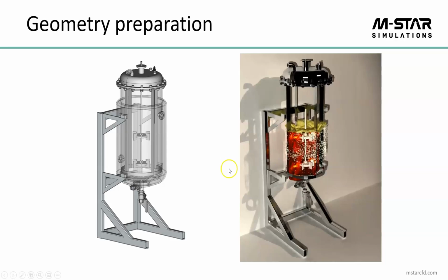If I were in the lab, I might use a laser or LDA to characterize the velocity at one point. I might add some dye to characterize the blend time. I might use a torque cell to characterize the shaft impeller. I might use visual inspection or video to characterize the vortex depth. We do the same thing in digital twins. We characterize data in the exact same way.